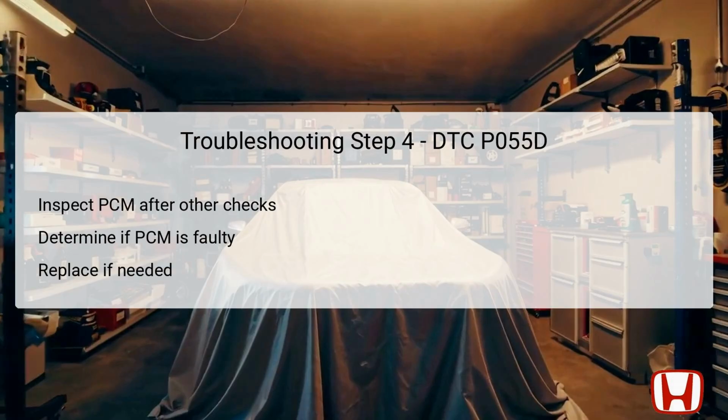This electronic module is responsible for interpreting signals from various engine components and managing engine performance. If the PCM is identified as the root cause during tests, replacement may be necessary to restore proper operation. It is crucial to follow up this inspection with accurate tests against the manufacturer's specifications to validate its performance and ensure the problem is resolved.